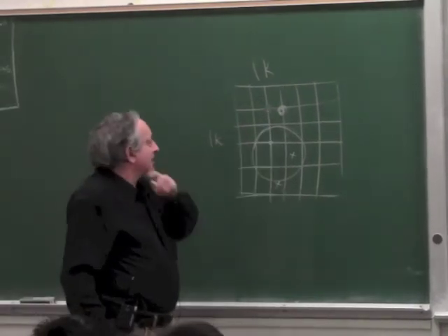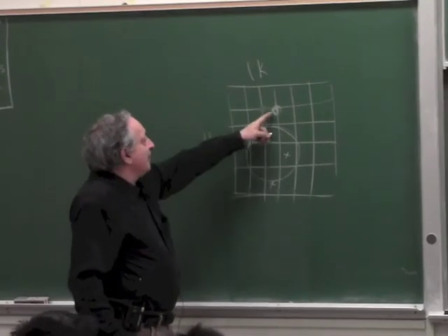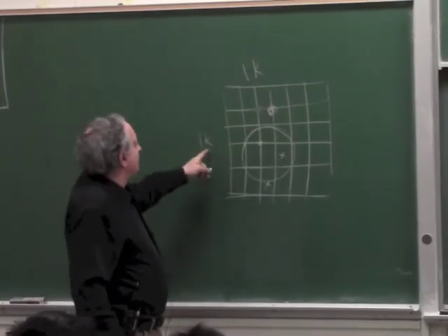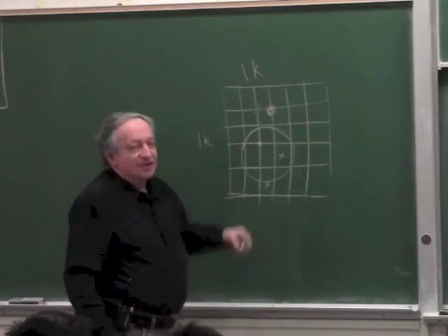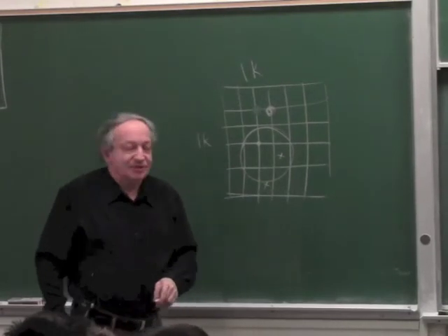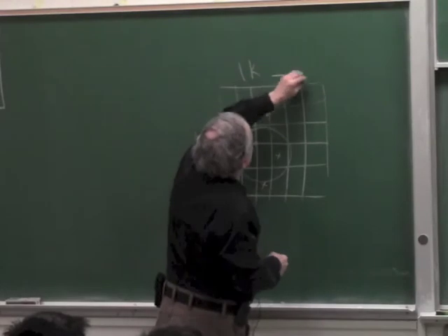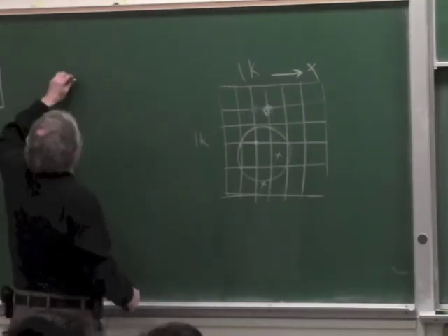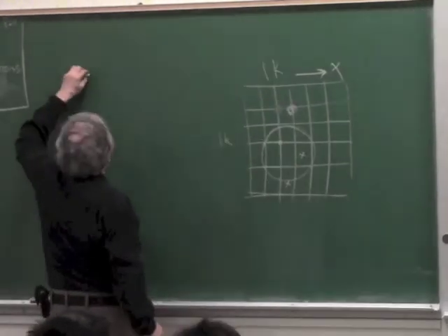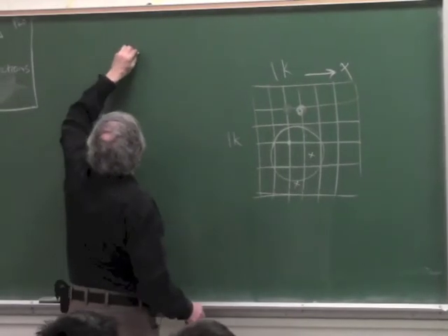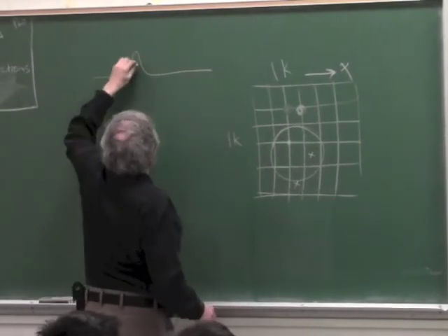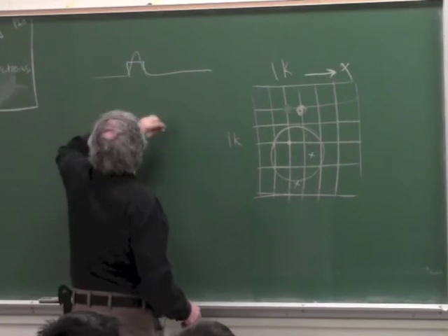and we talked about early quantization, you can only have a resolution equal to the number of rows or the number of columns, right? Because if you use a small spot and the spot is moving, let's say in the X direction, you will get the following readout. The first time you'll get a readout like this, and you'll quantize it. You'll make it a 1.